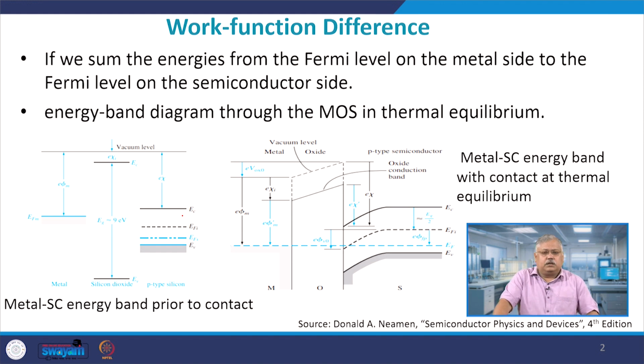and p type semiconductor. And as the Fermi level becomes closer to the conduction band near the surface, electrons get added there, and as you move away from there, you have a depletion region being formed there. This we have taken away from a previous slide.